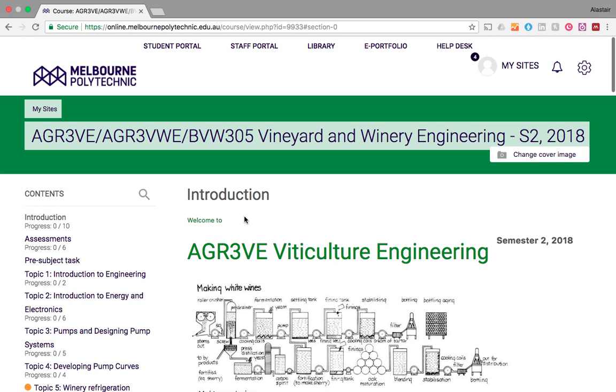The static head, quite literally, is the difference in the height of the liquid in the supply compared to the height of the liquid in the discharge. And that allows us to work out how much gravity needs to be overcome. So it's literally the vertical distance that the pump needs to overcome to move that liquid. So if the liquid's 2 meters in the supply tank and 4 meters in the discharge tank, the static head would be 2 meters.